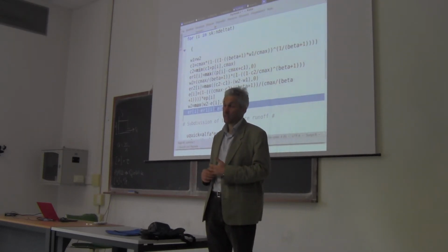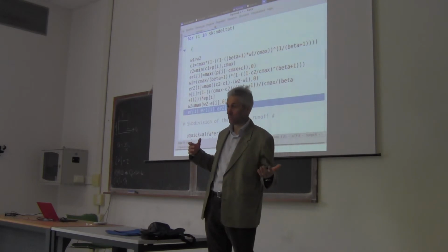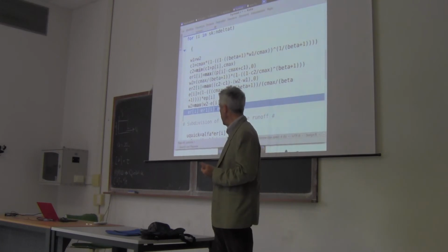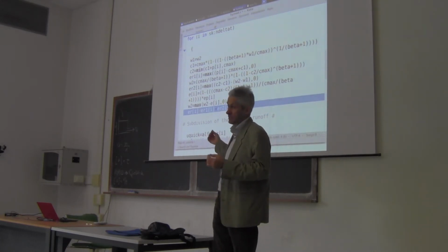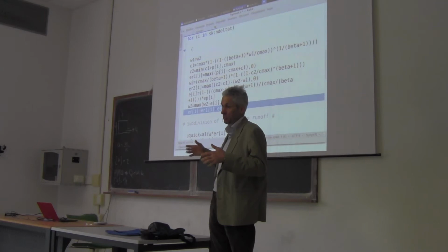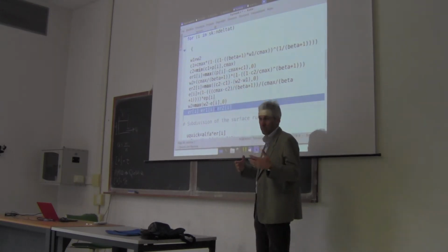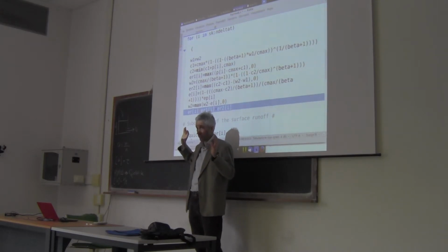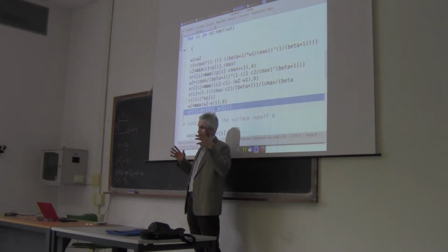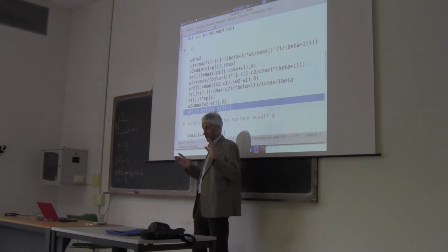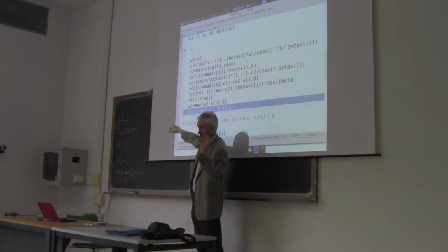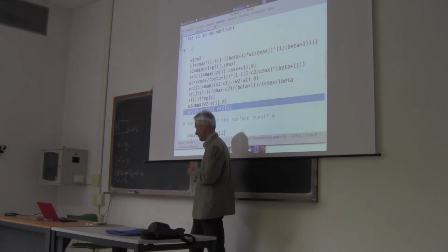It's a runoff, so we are expecting something like volume divided by time. And if we get millimeters per hour, it's a length divided by time, so we need to obtain cubic meters per second, we need a conversion factor here. Okay, the same conversion factor that we defined above. But let's focus on it because we found a small inconsistency in the conversion factor. So let's make sure that we are aware of the unit here. It's millimeters per hour. Okay, good.